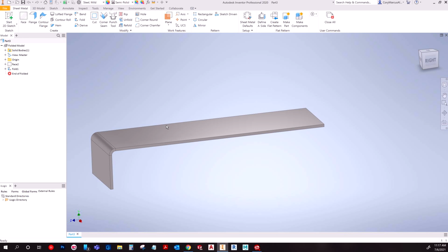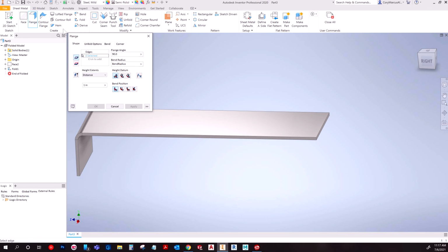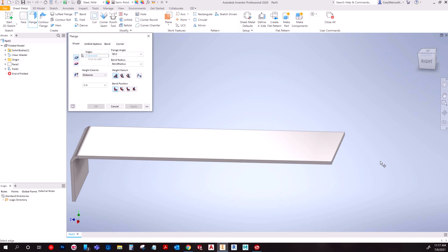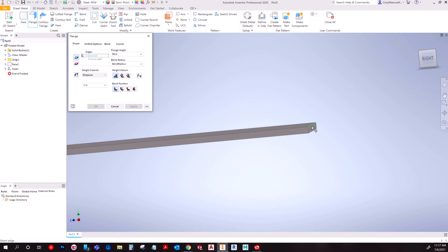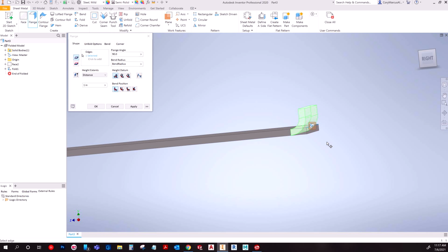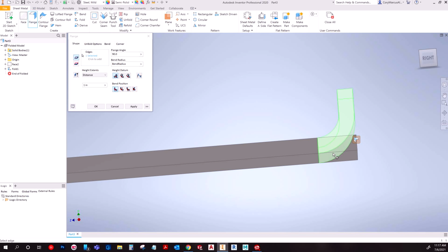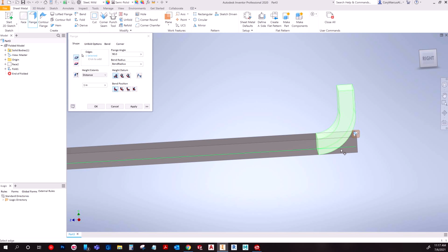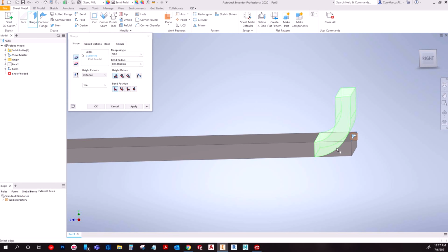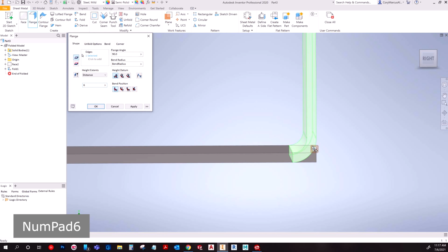But you can also do the same thing without having to actually make the flat part. Flange. Flange is probably the king of sheet metal. All you do is choose an edge, and let's choose this one. We're going to bend it upwards. From here, all it does is cut off what you would consider the outside setback. If you're looking at it, you can see that's clearly the OSSB. And then it gives you an option to give a length. So I could say it's 6 inches long.